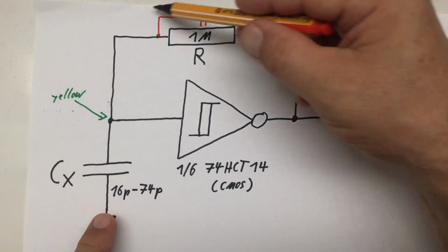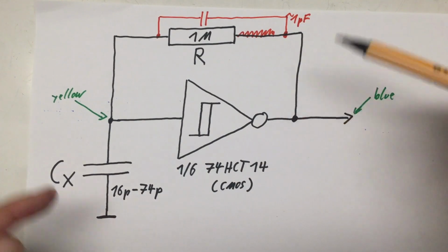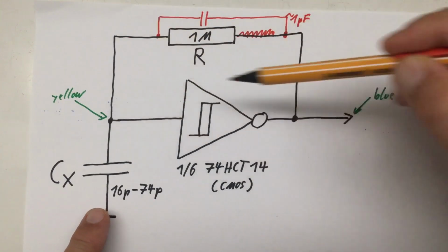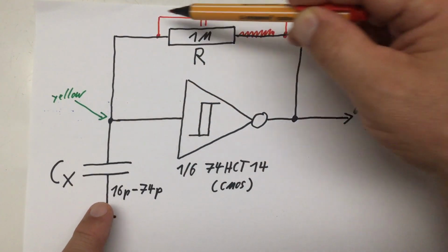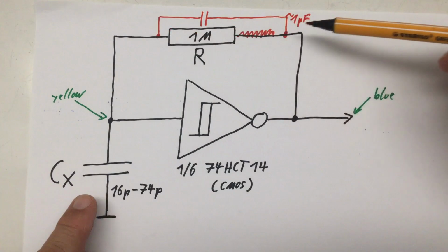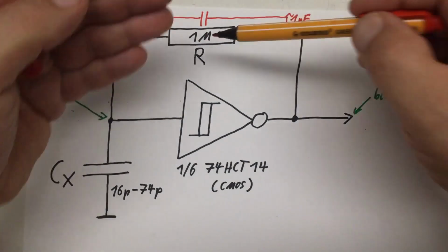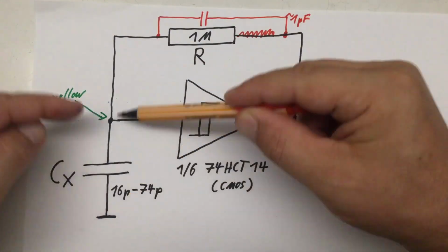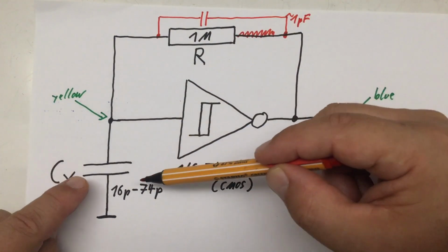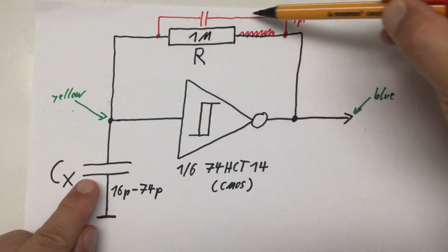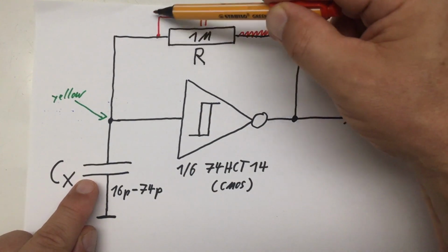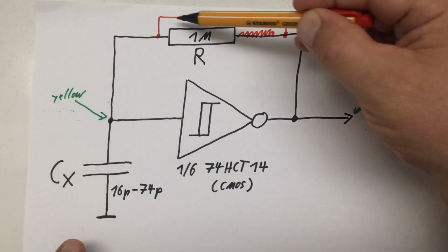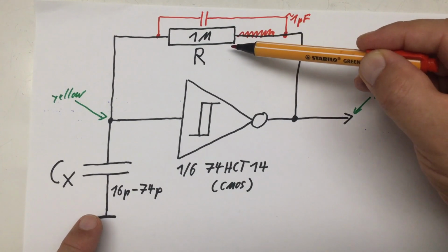So in relation to our capacitor here, when we are dry at 16 picofarads, that's quite a current pulse we can get through this resistor, which is in that case not acting as a resistor but as a capacitor, and have this initial voltage jump, until that parasitic capacitance of the resistor is charged and the resistor is really working as a 1 megaohm resistor.